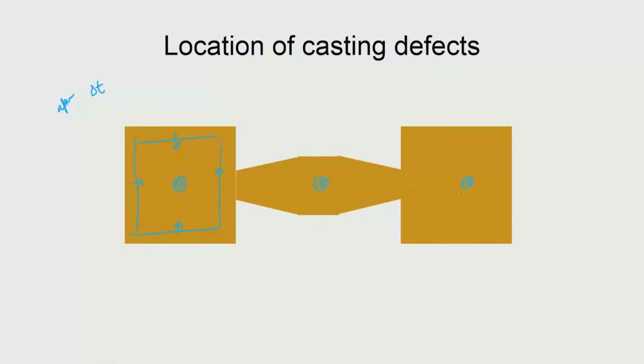You would also see that this distance is small compared to the entire thickness, which means that you would actually block this direction for liquid flow very early, which means that the last to solidify liquid here has to solidify, and if there is a shrinkage, then that shrinkage will be visible here because there is no feeding of liquid from elsewhere. Okay. The same thing is a problem here, okay, and problem here. So, like this you can actually identify by geometrical constructions.